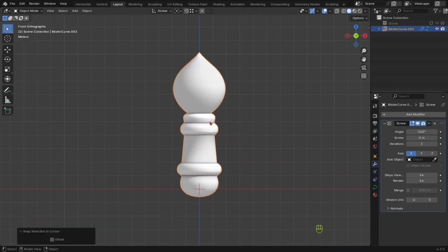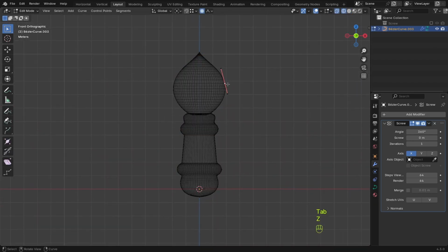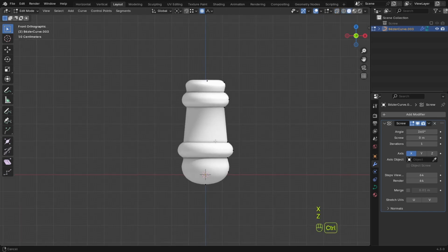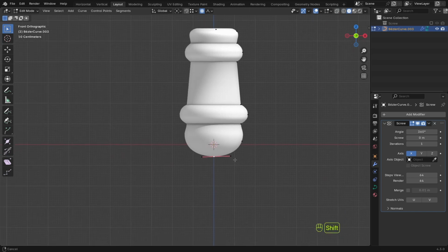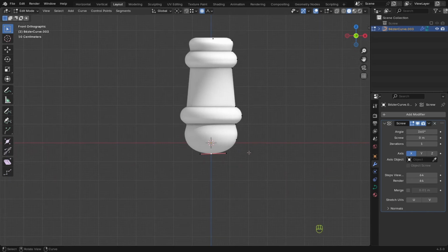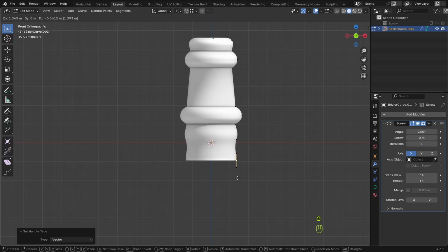And I'd like to convert this one to something else. Let's press L, select the vertex and press L and just remove the vertices. And yeah, let's shape it to something else, because I have a good plan for these. We can press V to set it to vector, or let's turn this proportional editing off for a second.